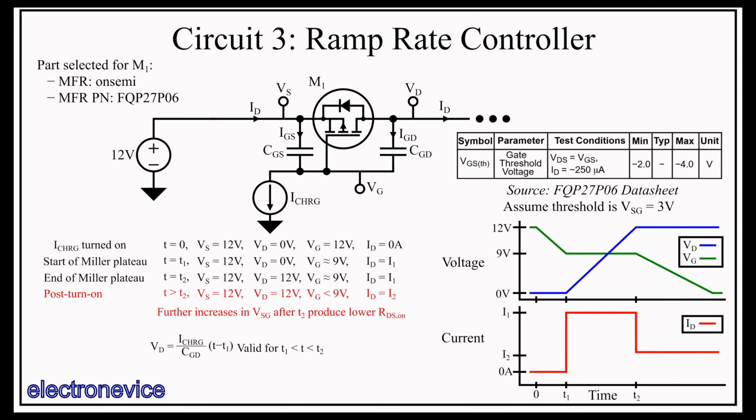we usually want to use the total gate charge rather than the actual capacitors, because the capacitors change so much during turn-on that it's simpler just to assess the total charge that must flow into the gate during turn-on. But we can do a simple if brutal way to linearize this gate-drain capacitance, which is simply adding a much larger capacitance in parallel to it that swamps out the variations and makes them negligible. This generally has the downside of slowing down the turn-on of the FET, but for this circuit we actually want that turn-on to be pretty slow, on the order of milliseconds at minimum, and so this will usually not be a problem.